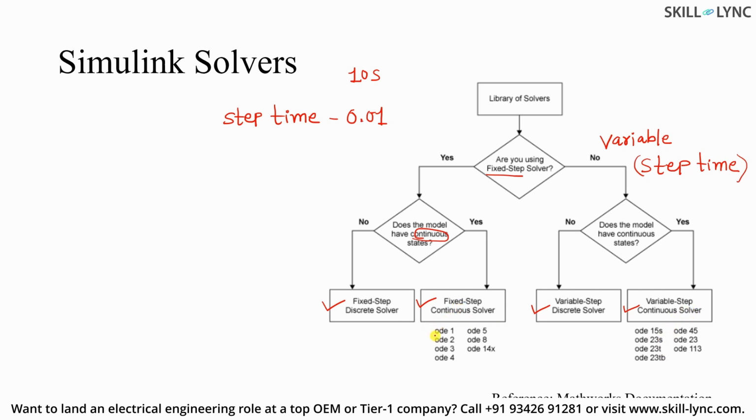They are classified under different names, and these names are nothing but ODE, which stands for ordinary differential equation, of first order, second order, third, fourth, and so on, right? Here you have a variable step continuous solver, an ordinary differential equation solver of 15th order, maybe 23rd order, and the S and T stand for stiff or non-stiff. So these are Simulink solvers.